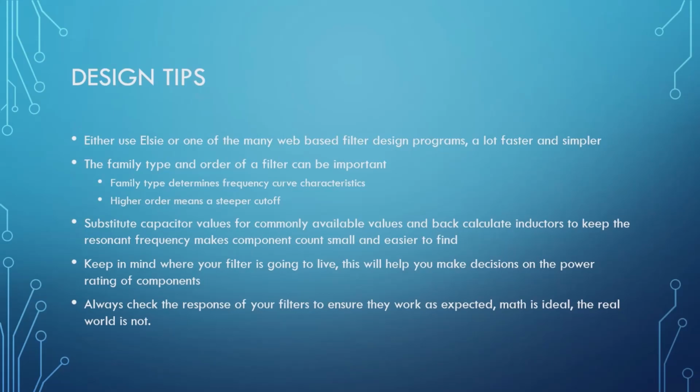Yeah, so I was thinking from a surface mount part standpoint for the capacitors. So if we're going to wrap our own inductors, you can theoretically wrap close to whatever you need. So in that case, you'd want to choose your capacitor first, and then calculate your inductor, and then how many wraps you need, what your toroid width is, and all that kind of stuff. Well, and actually, I'm going to show you a cheat sheet that does it for us.